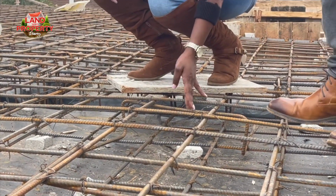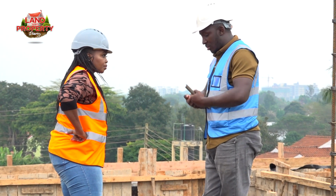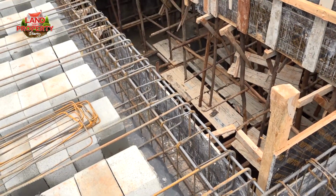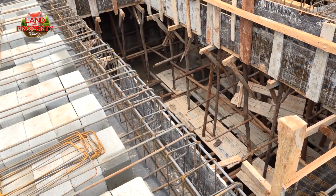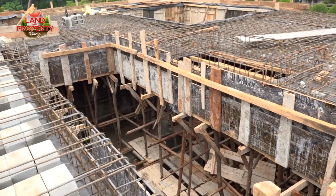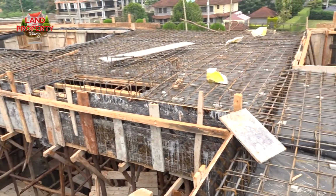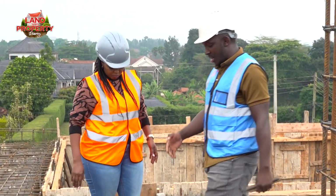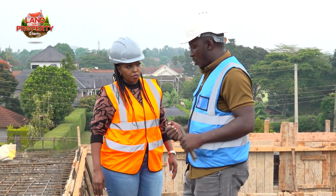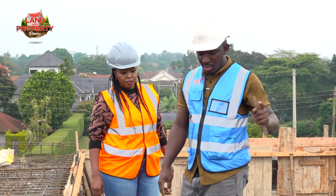For the bottom part, it's used to carry the tension, so the chini slab, and take it to the beams. Okay. Where we are seated, we were doing hollow pots. Now for this solid slab, it's going to be reinforced both ways, chini na juu. These reinforcements distribute the load. Like when I stand here and it's already covered in concrete, my load will be taken by the slab to the beam. To the beam. And then from the beams to the column.